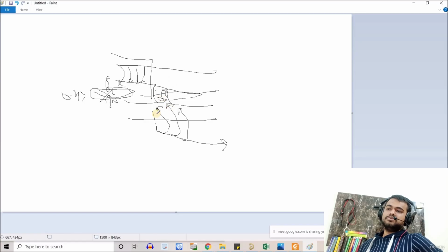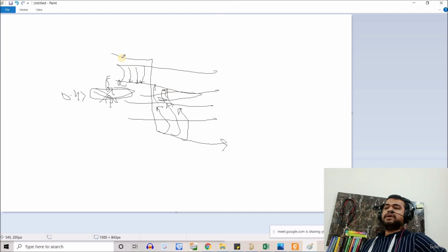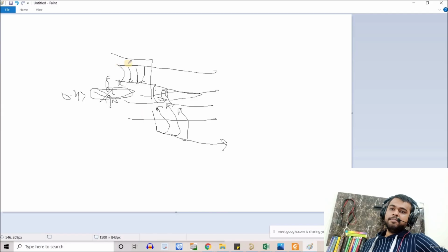So it will spread around the PCB and try to search for a low impedance path. In that case, what will happen? The return path will see a high impedance, and because of that there will be a ringing problem, or it can interfere with the other tracks, because it will start radiating while searching for a lower impedance path.